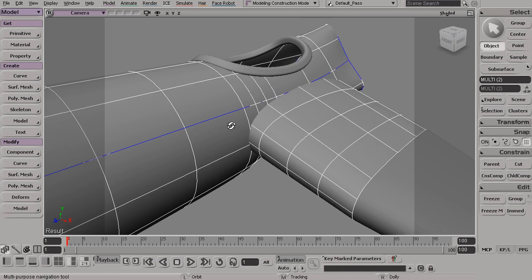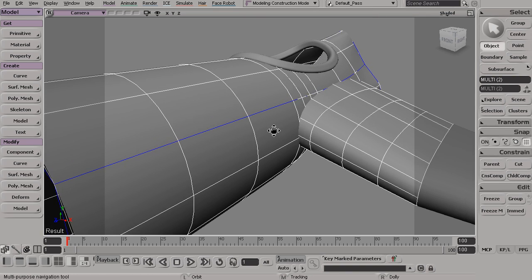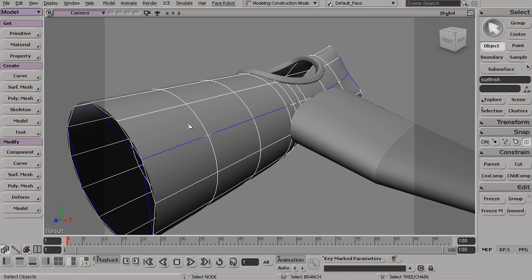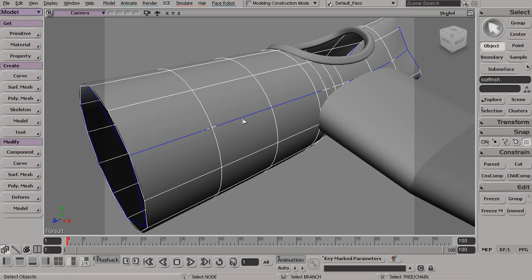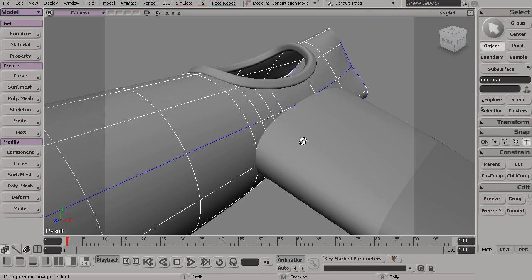Now, before we attempt to build this, there is going to be a little bit of a problem that we run into, and that is with this aircraft main body. You can see that we have this blue curve that is running down the length of the aircraft. This is essentially the seam in the geometry. It is the point where the piece of geometry loops back around and folds back to touch itself. This seam has always been present in the geometry. It's just that by doing the trimming, which we did in one of our earlier lessons, it's now made this seam much more visible as far as the display goes.